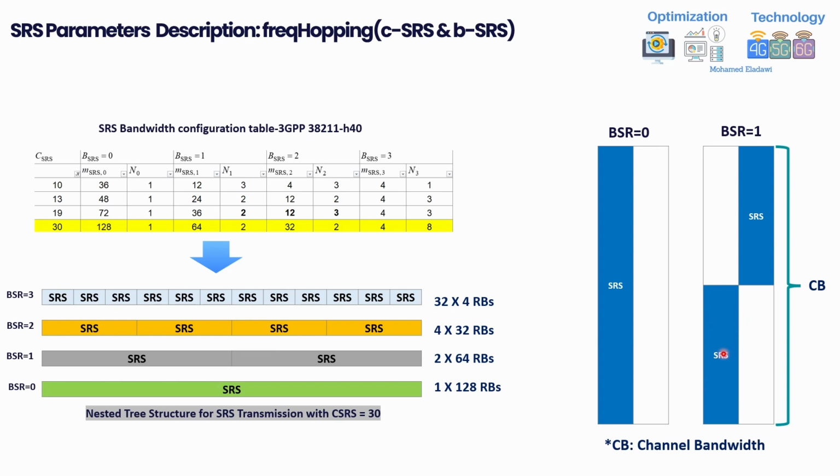So you can have maybe up to 3 dB improvement. This can improve your uplink SRS coverage and quality by around 3 dB. But still there are some associated drawbacks that can be observed, not necessarily, but can be observed: you are still not reporting the full bandwidth.